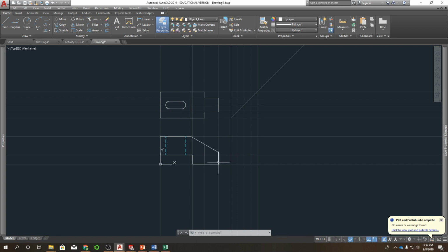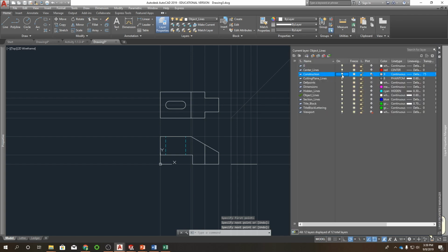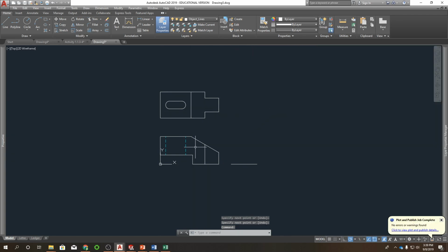So we have a surface here that starts right there and goes back to there. This line here, that's the starting edge of this cutout. So knowing that it goes from here to here, we know that a bottom edge is going to be all the way across. I'm going to shut my construction lines off for a second. This part's kind of symmetrical, so we have the surface facing the front and it's also on the back. So I'm going to do a quick hatch here.